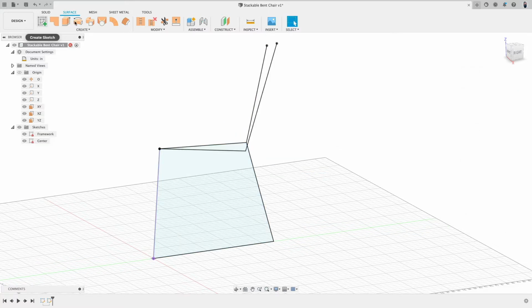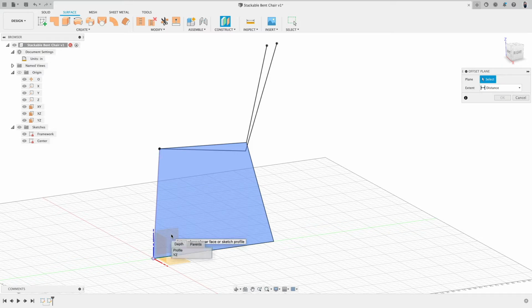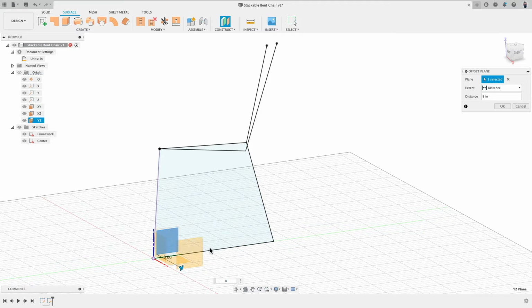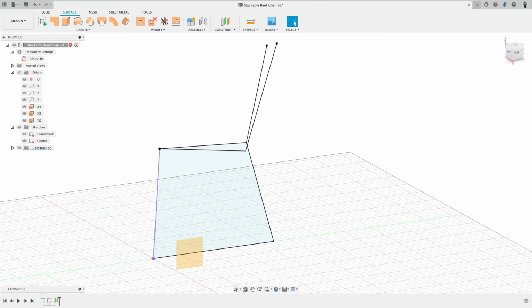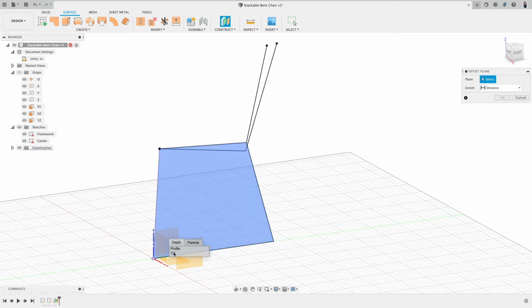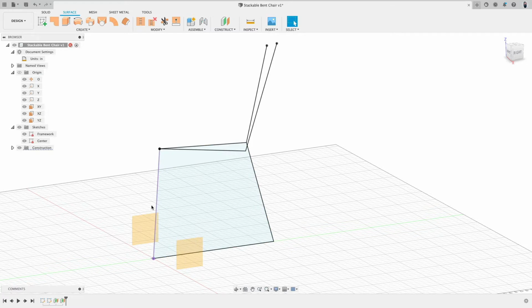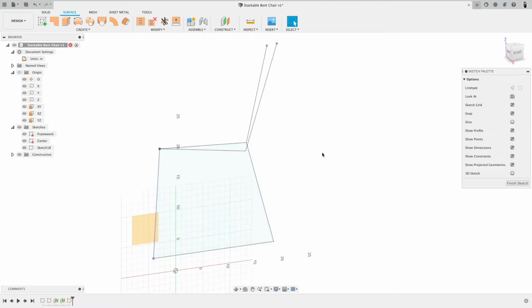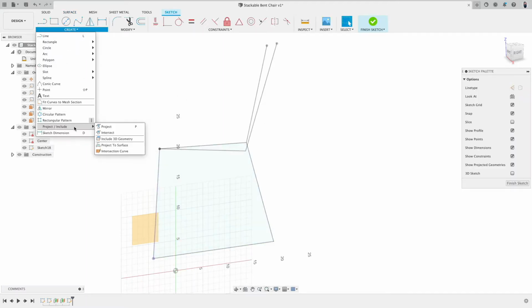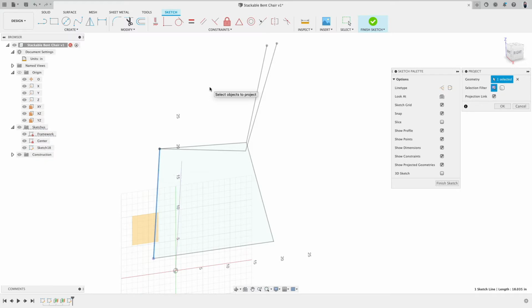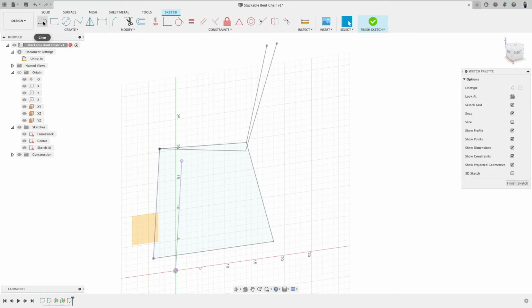So let's create those. So before we create the sketch, we need to create the construction plane. Left mouse button, click and hold, select the YZ 8 inches, and then right click, repeat, click and hold, YZ minus 8 inches. You see also here how I nicely group my commands. Now I will create a sketch here. I will just project the front piece in. That's actually what I will use. I'm not sure about this, if this is perfect. So I will not project these elements in, but simply redraw this by hand.